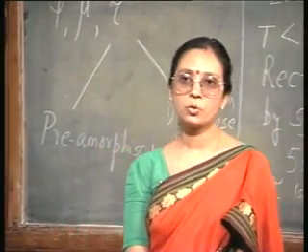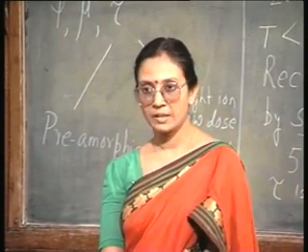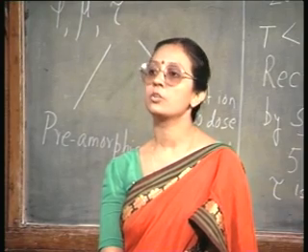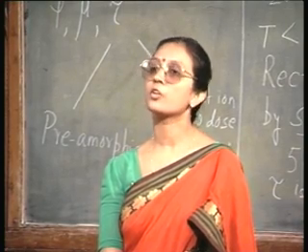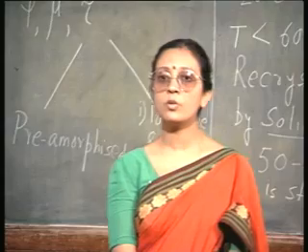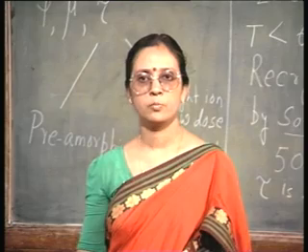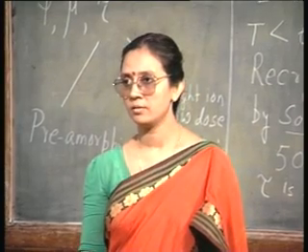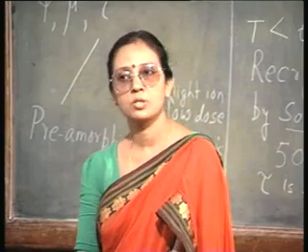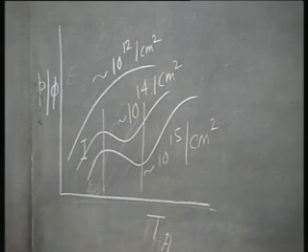However, as I go to region 3, that is, as I increase the annealing temperature, you are creating a lot of vacancies. You are supplying a lot of thermal energy, and therefore, you are promoting vacancy formation. So, now there is enough place for boron as well as for silicon. Boron can get back into its substitutional sites and therefore, the active carrier concentration also increases. So, this is the annealing behavior of boron.